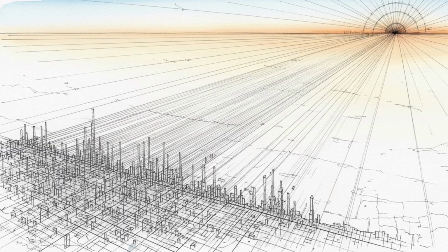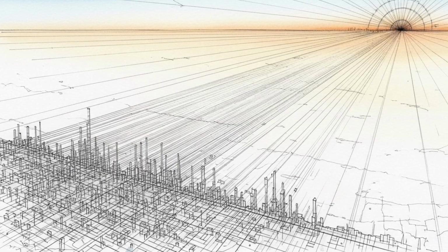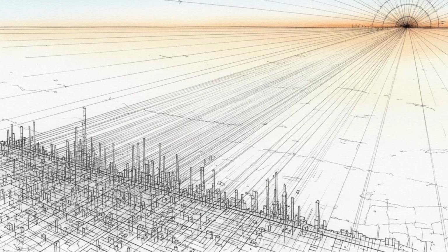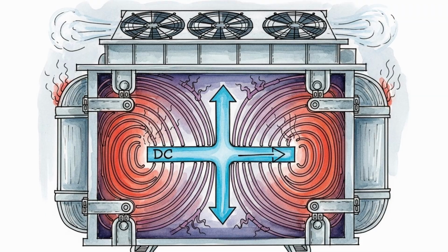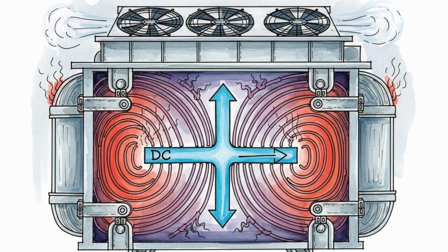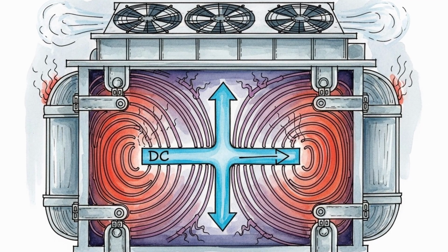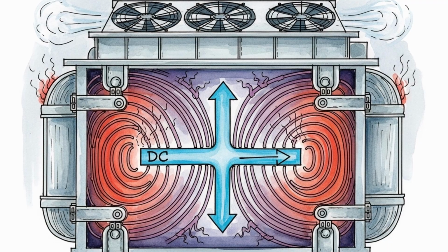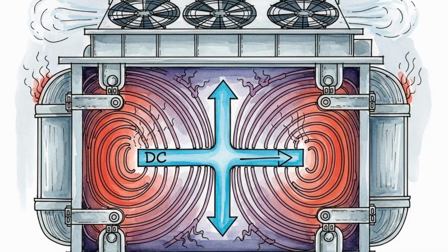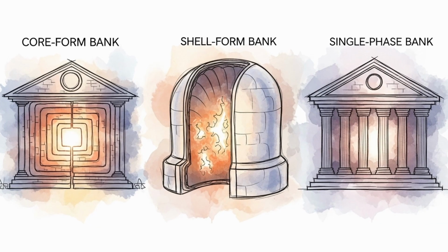The rate of change of the ground magnetic field is a primary driver for induced currents. Engineers refer to it as dB/dt. Large absolute field changes matter, but the fastest ramps are more important for geomagnetically induced currents in long conductors. When the field changes quickly, an electric field is produced in the ground. This electric field drives quasi-direct currents into grounded networks. The direction and strength vary by location and by the orientation of the conductors.